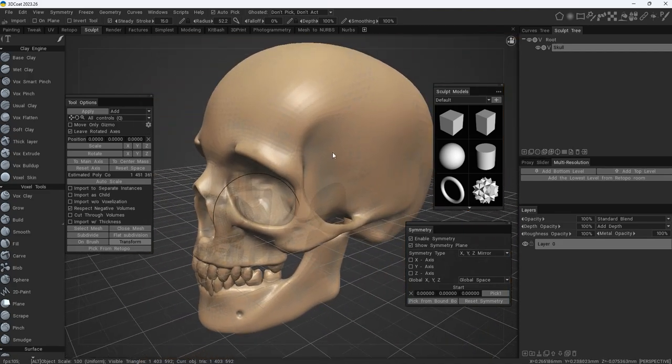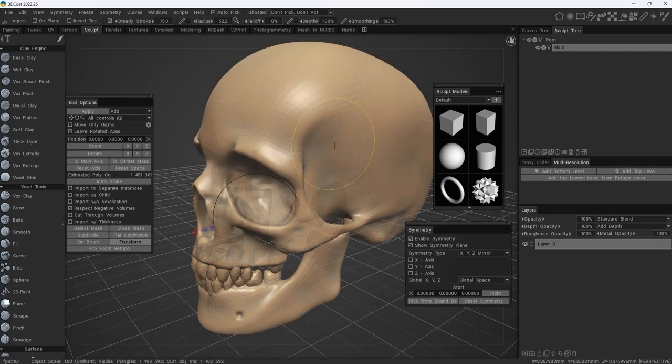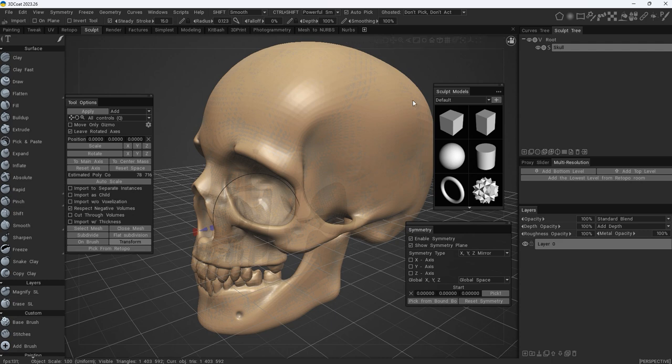Okay, if your model doesn't have enough detail, it probably means that you don't have enough faces and voxels inside. So you can just simply enlarge your model. If your model is bigger, then you will have more voxels inside, but it will also increase the load on your laptop. Okay, but what's the thing I mentioned before? We can switch between Surface and Voxel. You can just simply click this button, and now this model has been switched to Surface.